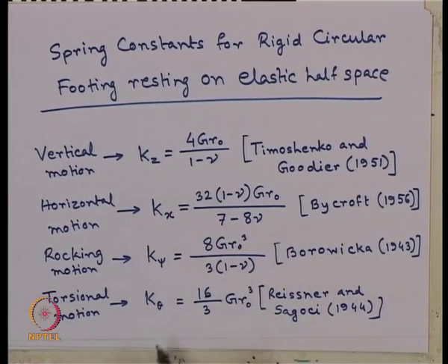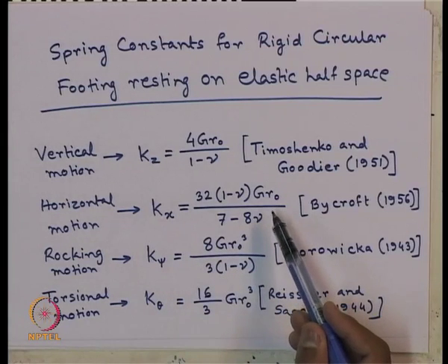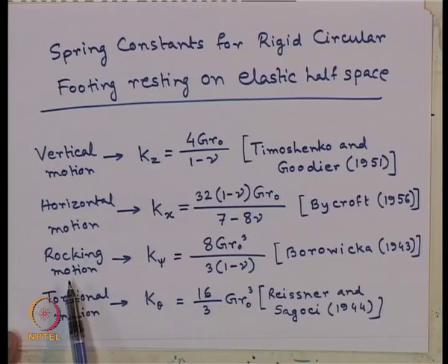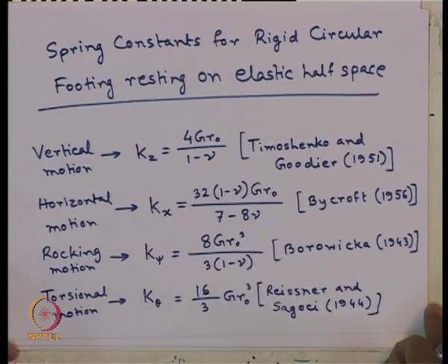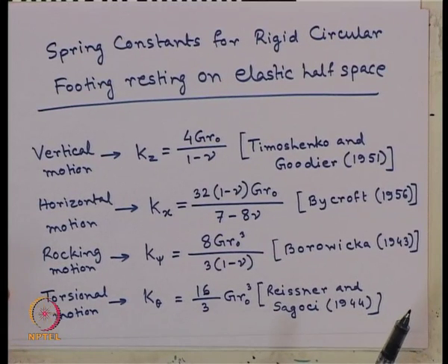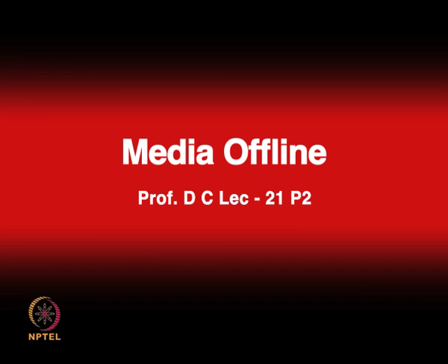So, these things can be obtained for different modes of vibration. For horizontal motion, as you know, it can be kx or ky both. Accordingly, the r naught expression will change. Rocking and pitching also same, calculation for r naught will change. So, let me give you the expressions for calculating the equivalent radius, which will help you to find out the expression for r naught correctly.